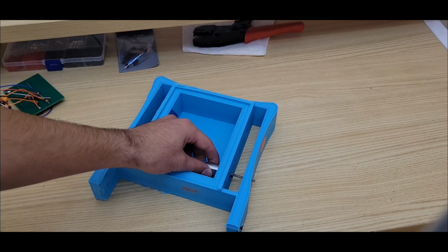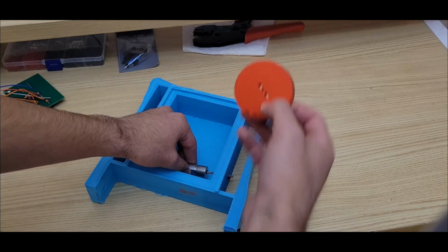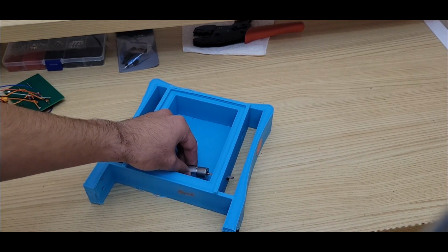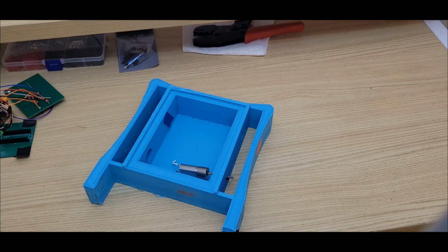However, I didn't design with assembly in mind, and so if I put the motor through, I can't fit the wheel in. If I put the wheel in first and then the motor, I would not be able to reach these 2 screws. This goes to show that it is important to think about how you're actually going to put the robot together during your design process so that you can avoid mistakes like these.